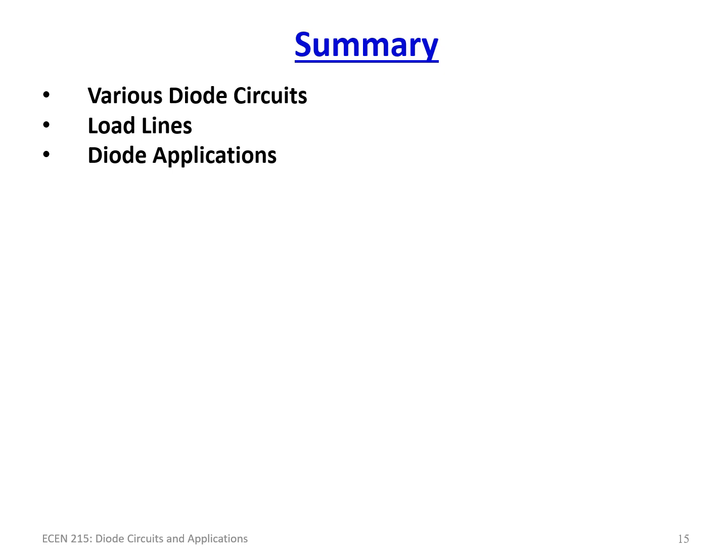We talked about being able to regulate an AC signal straight to DC, and then using that with the Zener diode to fully regulate to a nice clean 5-volt signal source. And then we also talked about LEDs and being able to use them for light emitting applications. And we talked about how you can compute the inline resistor for an LED given your specific design.